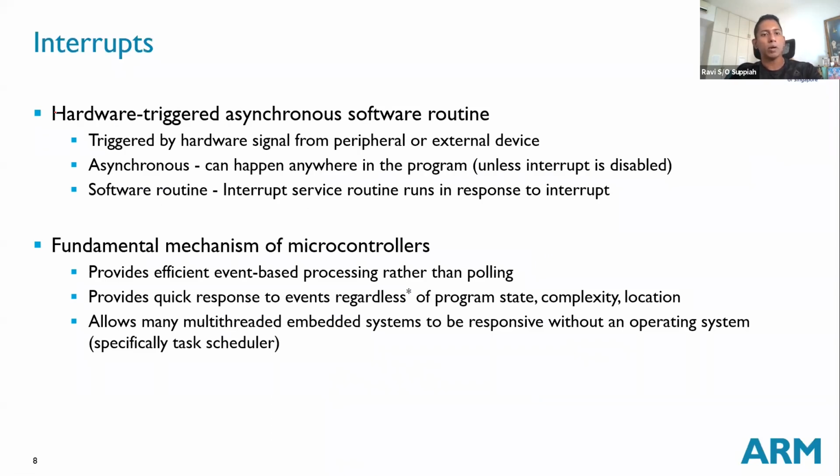In terms of triggering, it could be triggered by a hardware signal that could be external or internal. Internal means things like your timer blocks overflowing, or some other event within the system, maybe a DMA transfer. So within the system itself, you can generate an interrupt. External things are like your GPIO interrupts, or your serial port suddenly receiving data. It is asynchronous because it can happen anytime, and the moment it happens, you run the appropriate software for it.